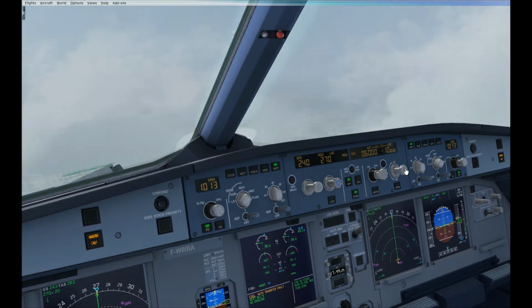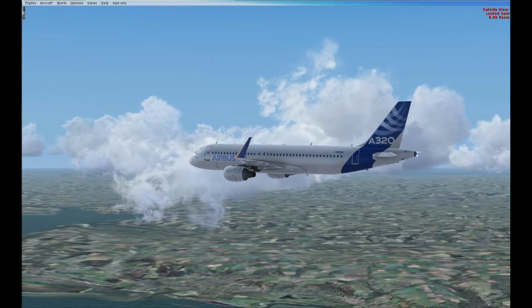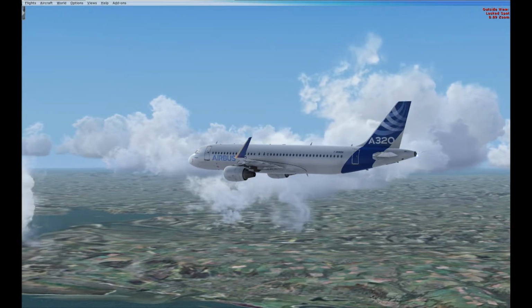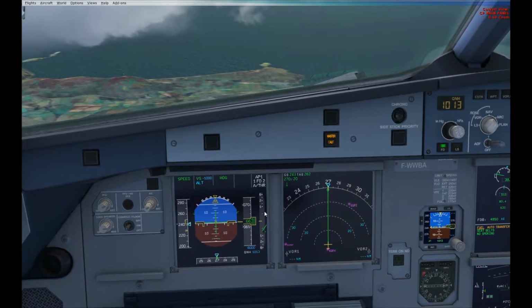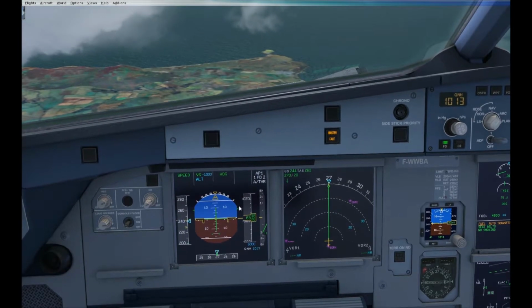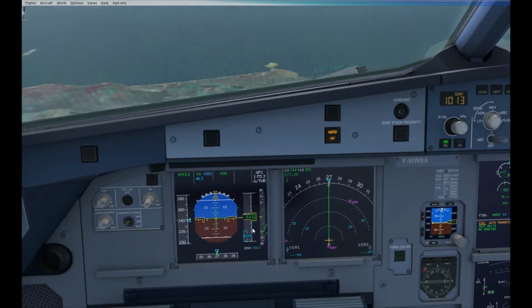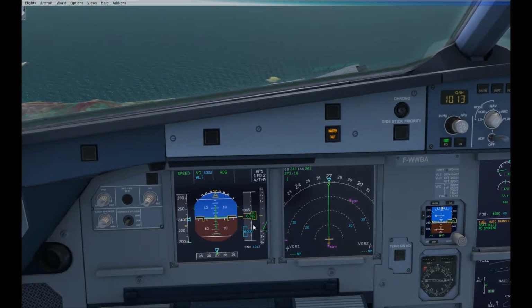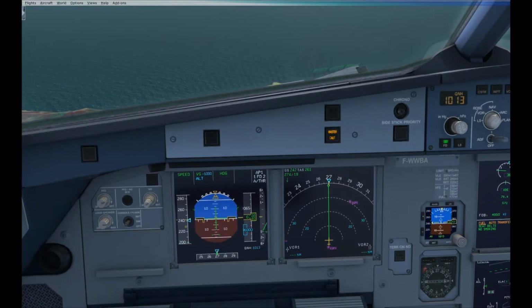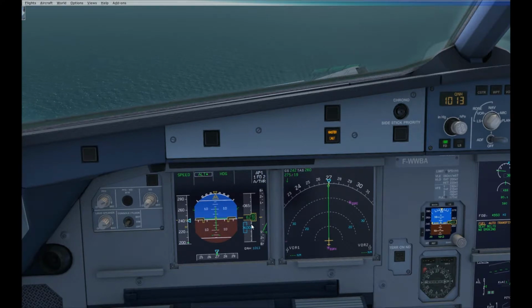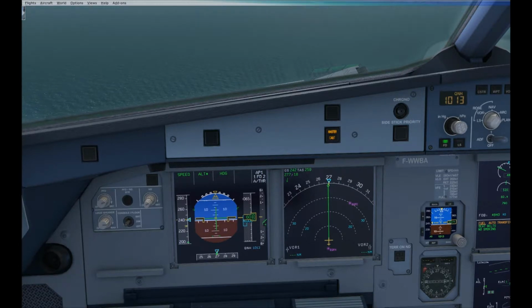We're descending here now, 6,006, 6,005. A little bit of turbulence, as you can see. 6,004. And when it reaches 6,000, it will level off once again. 6.3, 6.2. The autopilot will make this a very gentle transition into the various altitude settings. 6.1, 6,000. Still at 240 knots. Heading 270.